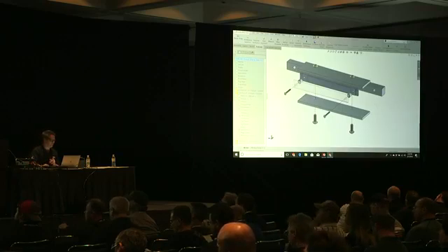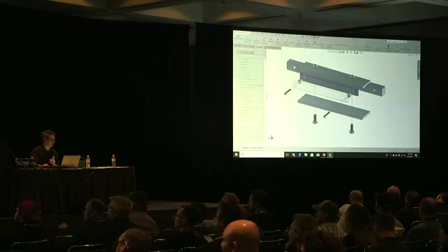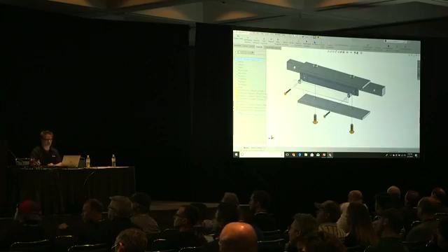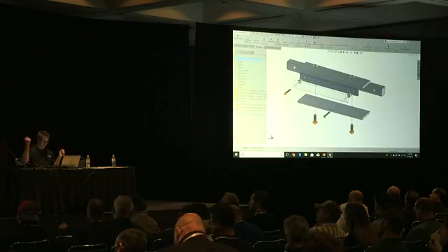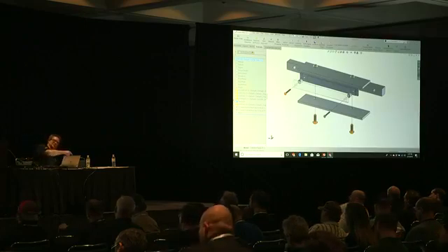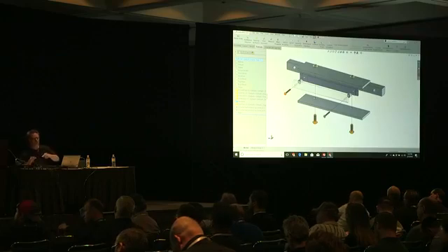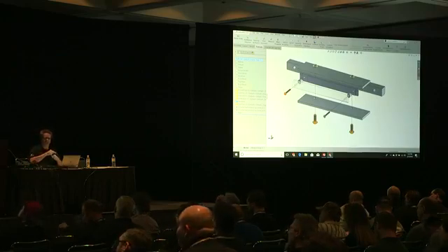This is one that, oddly enough, doesn't work well with a laptop keyboard. I ran into that the other day. I was planning on bringing a keyboard. So when your tree's all up like this, Shift-C collapses it. C is a pretty powerful one. Shift-C collapses, Control-C is copy. Control plus Shift-C is copy appearance. Alt-C is construction geometry convert. It's all in the book.